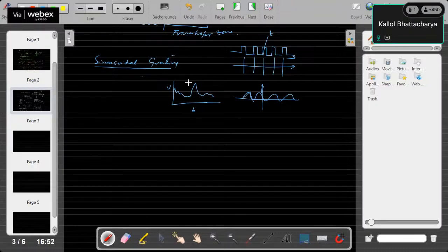If it is periodic, the harmonics will be discrete: omega, twice omega, 3 omega, 4 omega, and so on. But if it is aperiodic, then you will have an infinite number of frequencies. So the basic units are sine omega t and cos omega t, with which you constitute this particular function.